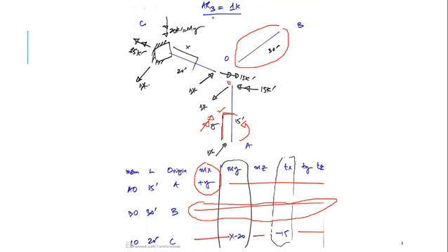That's it. Coming on to this section. The section is CO. Length is 20 feet. Origin is C. I have selected a section X. I have to find all moments forming here. This is 15 kip foot and this is along the member X. It should be balanced with this moment, equal and opposite, 15 kip foot. You should know that this member is in X direction and this moment is also in X direction, and it is counterclockwise.